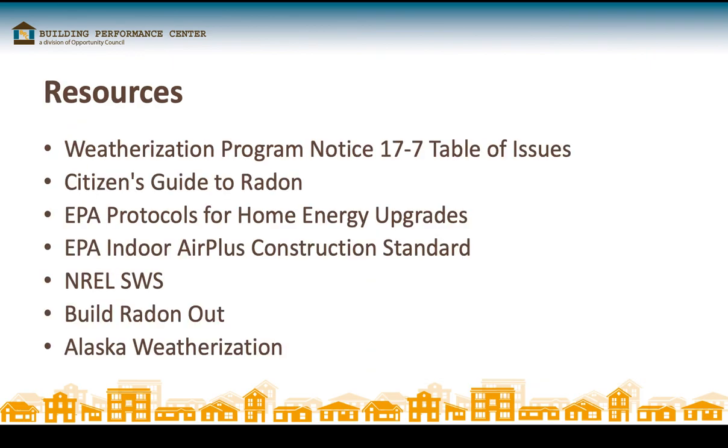All right, last but not least, we have some of the resources we used for this training: Weatherization Program Notice 17-7 from DOE, Table of Issues. We've used the Citizen's Guide to Radon. You're going to need to look up the EPA protocols for home energy upgrades. You also should look up EPA's Indoor Air Plus construction standard; they were telling us how to do ground covers with that. It's helpful, but not that helpful. The NREL SWS, the 2020 version, is really clear on precautionary measures. We also used Build Radon Out and Alaska Weatherization as some of our other resources for this particular presentation.